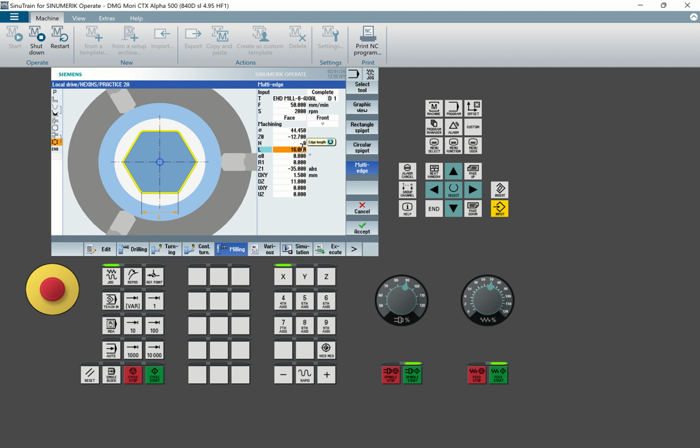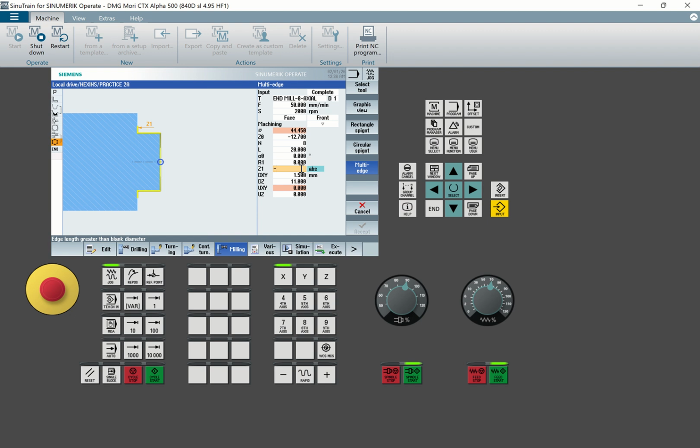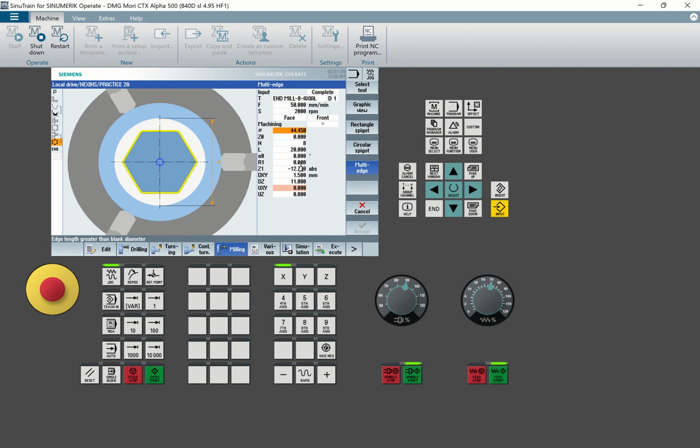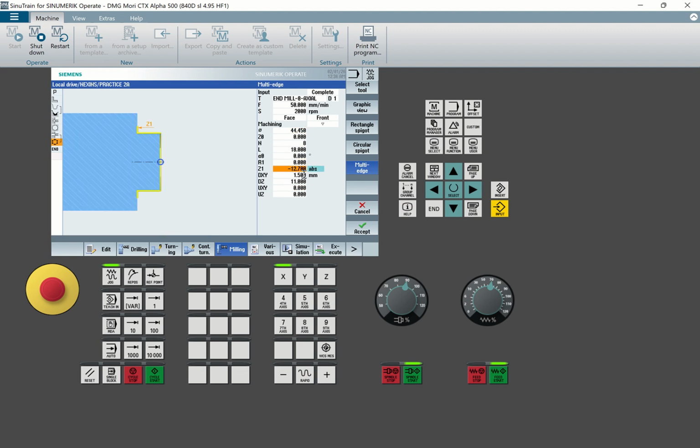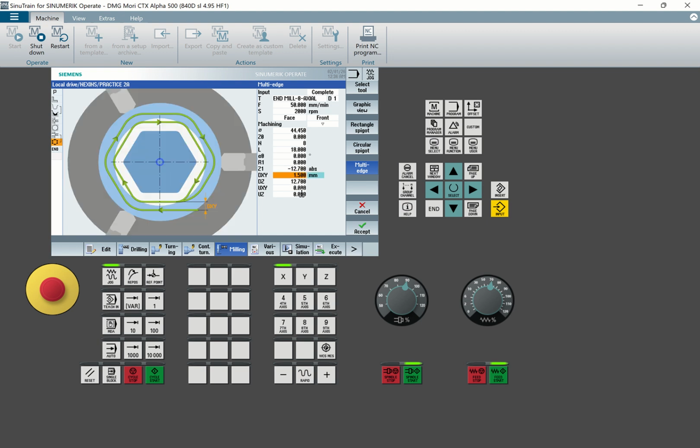The length of this can put even to be, let me say, 20. This one goes minus 12.7 from 0. Here I can put, let's say, like 18. You see, it goes inside. Then I want to put 12.7. The tool can go direct 12.7. So this is what I have. So on this diameter I want to cut this length, and then the angle can put to angle, let's say 45 for example. I'll show you, then accept.